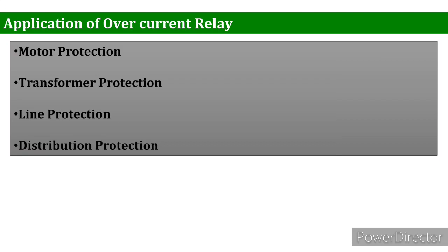Well, if we talk specifically about some of the applications of the overcurrent relay, I think it is very necessary to understand the complete operation of this overcurrent relay in our daily life or in industrial use. If we talk about motor protection, it is basically used against overloads and short circuits in the stator windings of the motor.